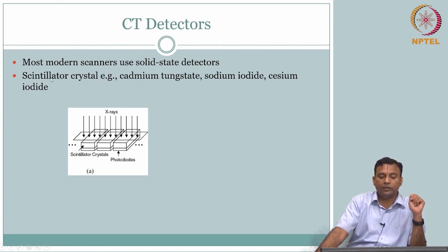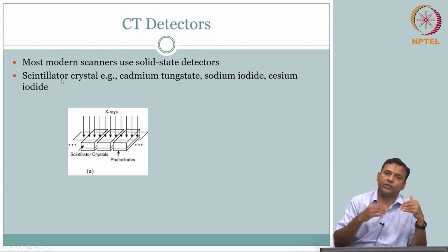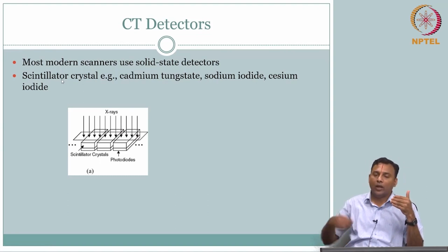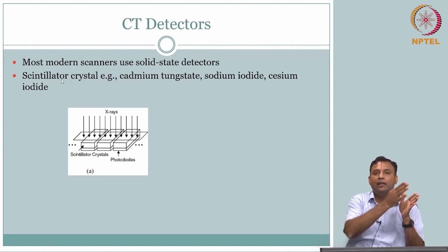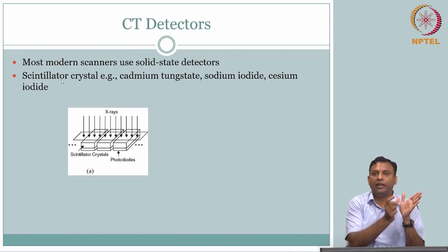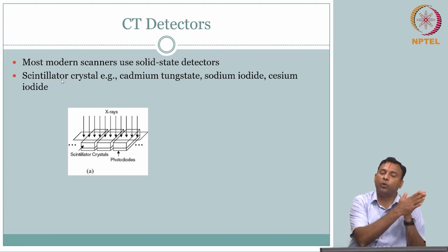So silicon, scintillator crystal, right, you might look at what it is. Look at the objective of the projection radiography instrumentation on the detector side. What was it? The X-ray photon came, it hit the photographic film, the conversion ratio was poor, and therefore they used some material, phosphor, an active material, right. What was it doing? It was the intensifying screen. Go look at that. It was trying to convert the X-ray energy to light energy, and that light photon went and exposed the film.